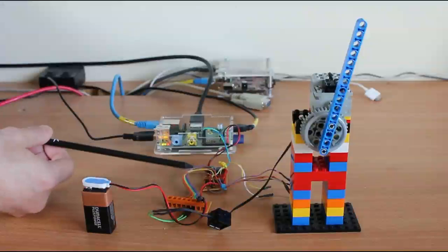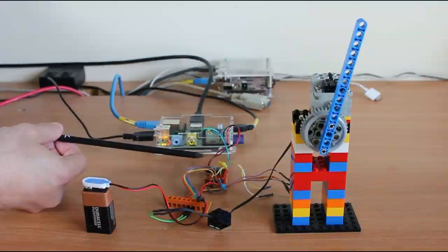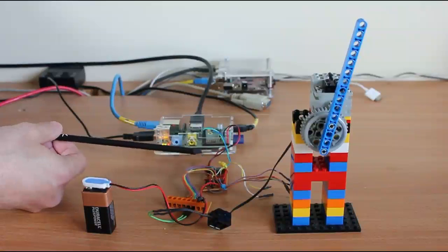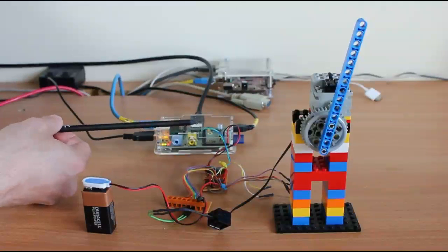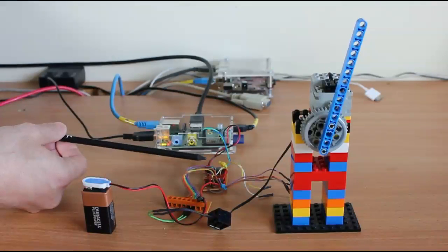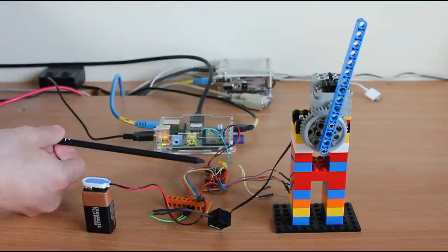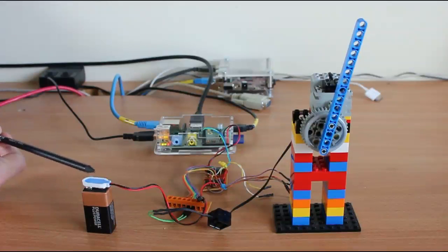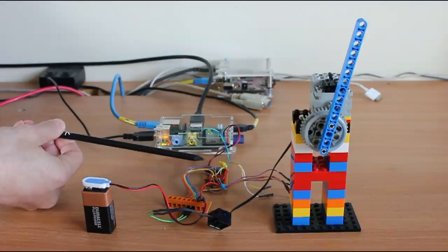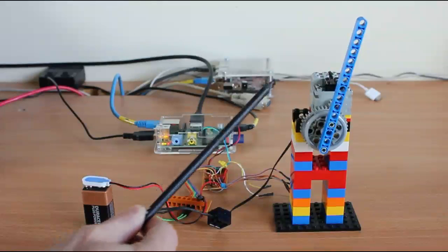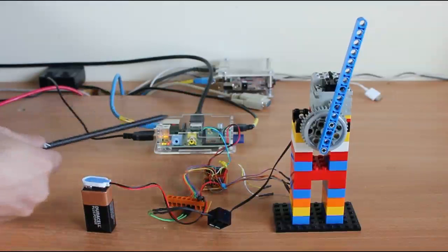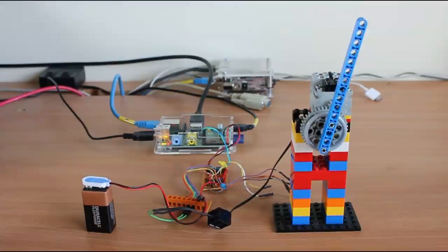These are fed to this little circuit board here, which contains a chip which is acting as an H-bridge. And what the H-bridge allows us to do is to control different voltages and significantly higher currents than we can do directly from the GPIO pins. So we feed the outputs from the GPIO pins into one side of the H-bridge. The other side of the H-bridge uses a plus 9 volt power supply here and can control a Lego motor. So the outputs come through to here, we feed the outputs to the Lego motor, and then from the Raspberry Pi we're able to control the Lego motor.